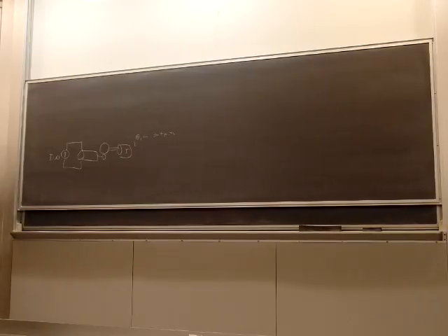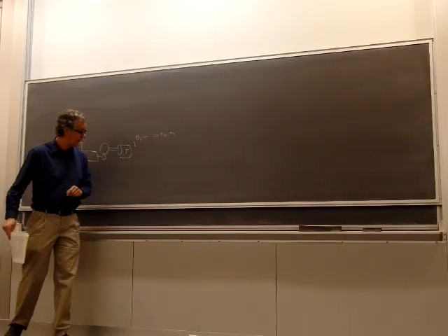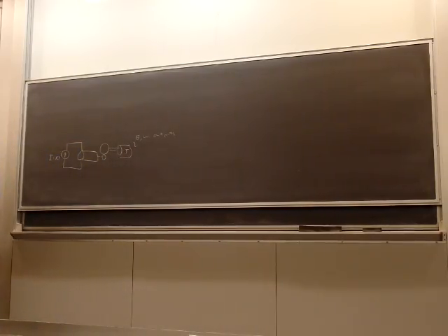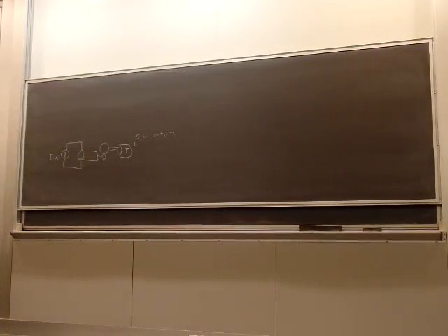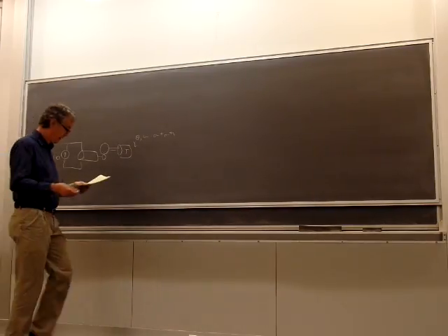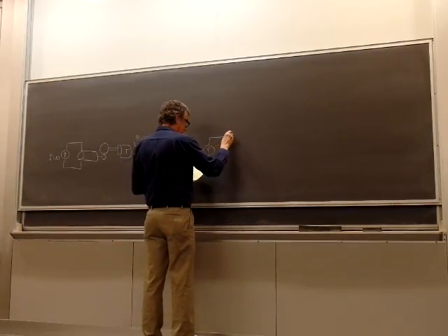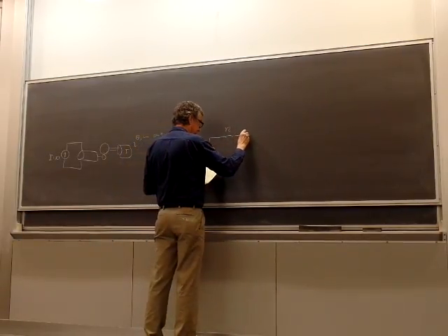Outputs are going to be just a motor system, little gearing, running a load, and we have theta and omega as our outputs in the system. Okay. First step is we're going to get the state equations modeled. This one's fairly simple. If you remember the model, I'm going to do this on the electrical side and the mechanical side. Motors have resistance and inductance.